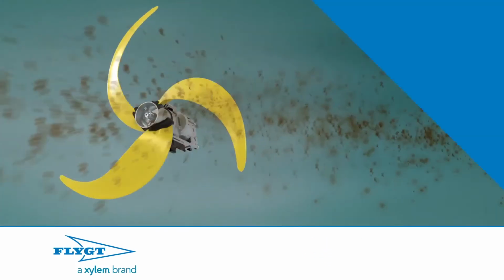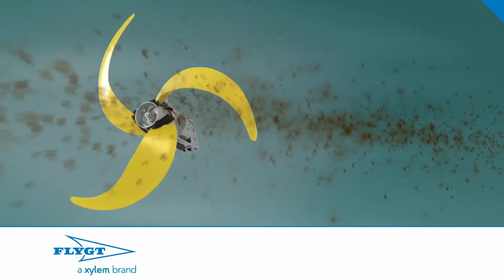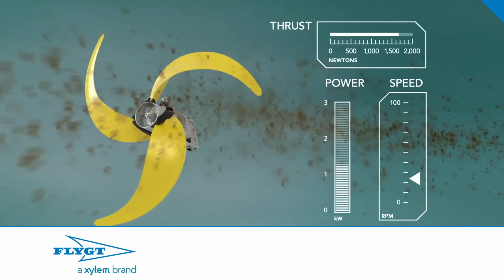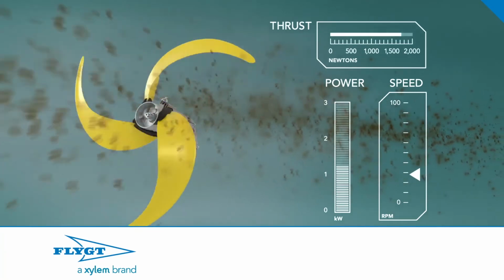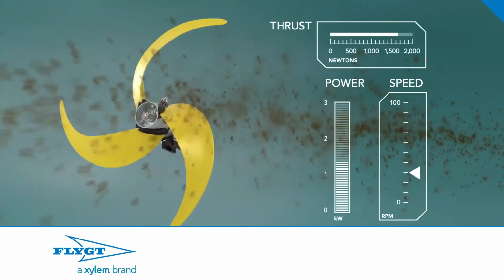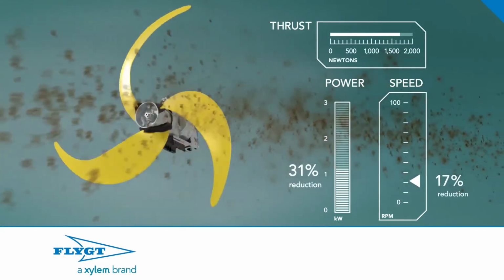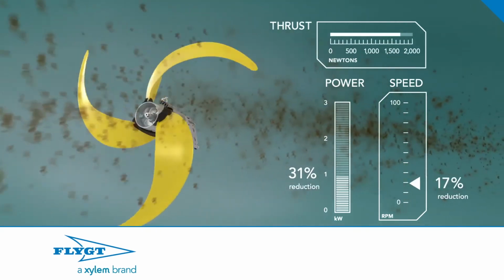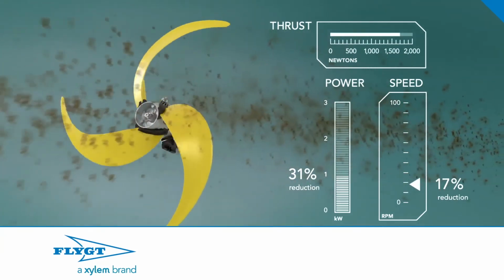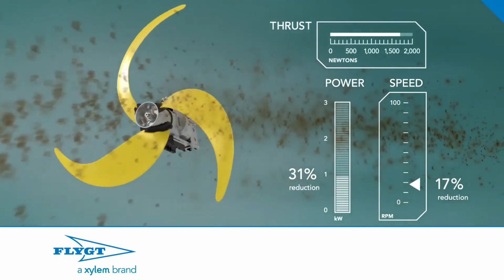A new world of possibilities opens up when you move to a mixer with integrated variable speed control, like the Flight 4320. First, the power consumption at any given speed drops dramatically, thanks to the high-efficiency permanent magnet IE4 motor, combined with the mixing intensity optimized for the actual operating conditions, using integrated variable speed technology. Second, watch what happens when the mixer starts slowing down to meet the actual needs in the tank. Small reductions in speed and thrust come with much larger reductions in power. These reductions in power and speed also can extend the life of the mixer and the intervals between servicing.